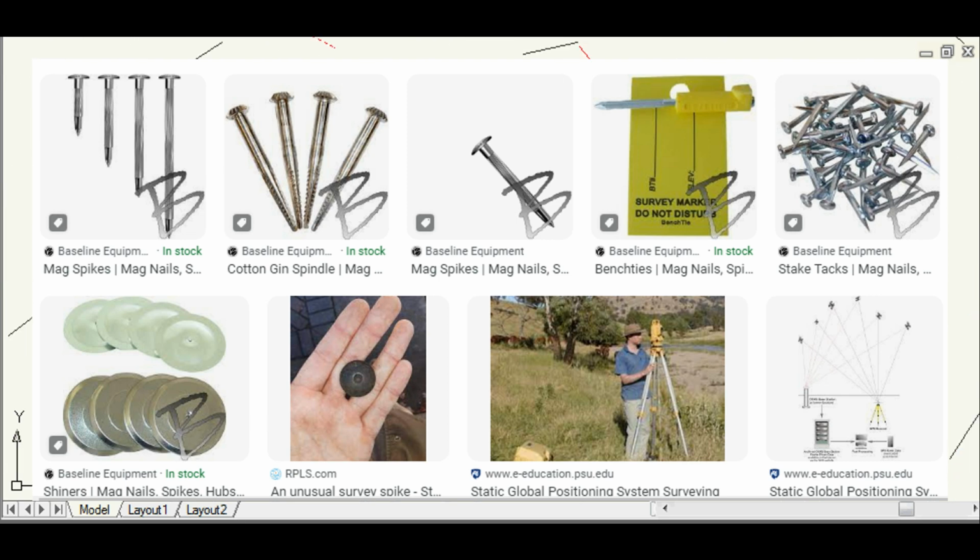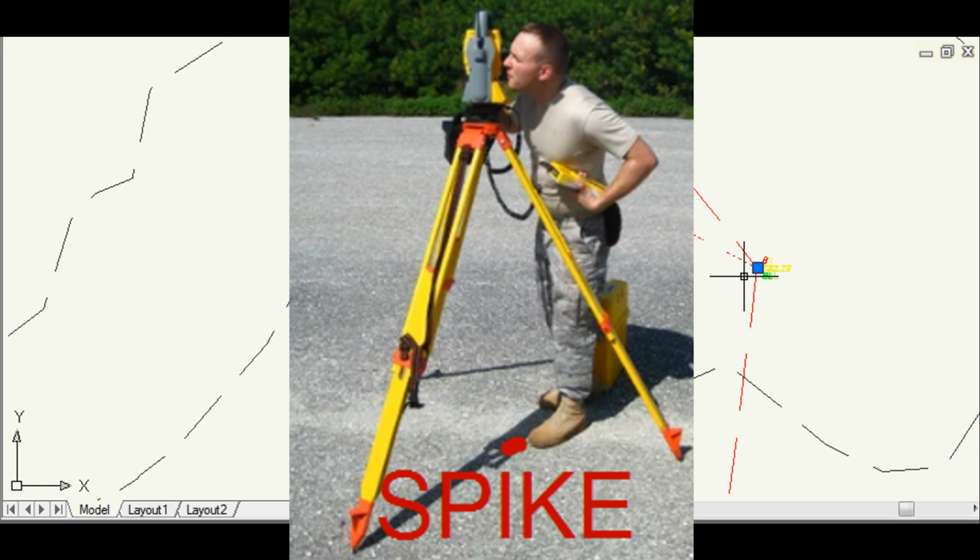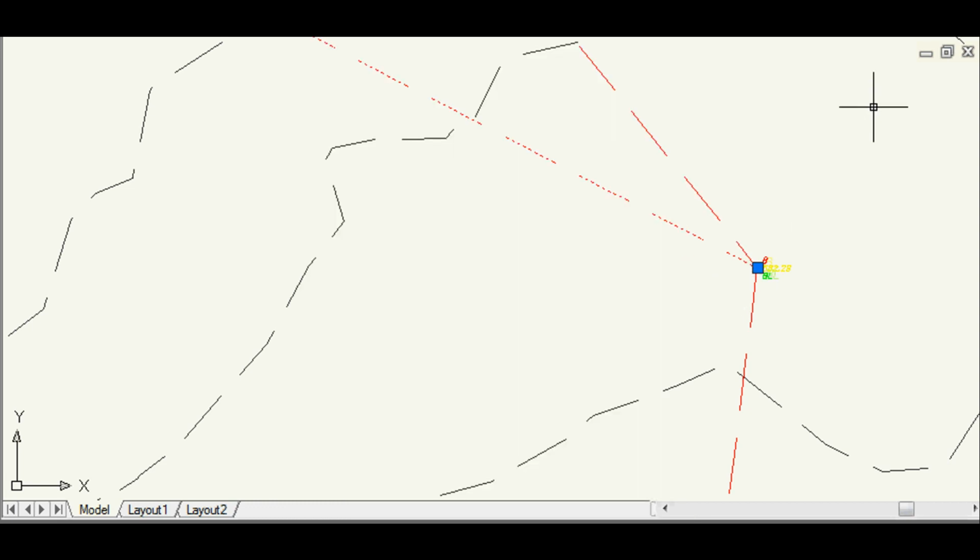And then our tripod sits over top of that perfectly vertical, perfectly plumb, so that our point is always exactly over the point that we're trying to measure. And then we measure the distance from the point on the ground to the bottom of the tripod, and we record that. And then as we go along, we can record elevation, distance, and direction with the instrument. And so that means we can actually record elevation data.